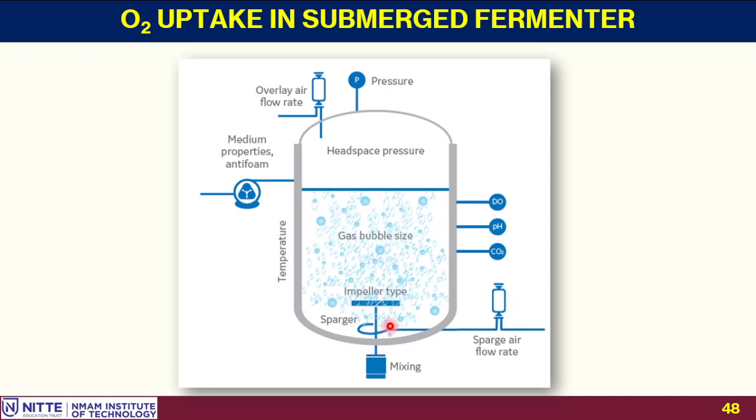The sparger, based on its design, produces bubbles of various sizes. The sizes may be very small depending upon the orifice size of the sparger. The bubble will be very small at the bottom, and as it moves up, there is something called the residence time, the time required for the bubble to reside inside and escape. The time for each bubble depends upon its size. The smaller the bubble, the more slowly it goes up. It depends on the sparger. But if the size is very small, it will require high pressure for operation. The flow rate maintenance will be difficult.